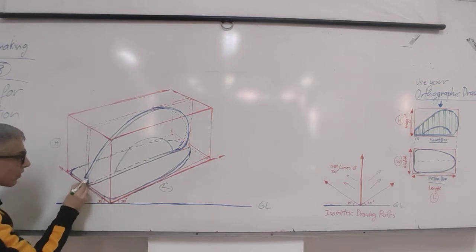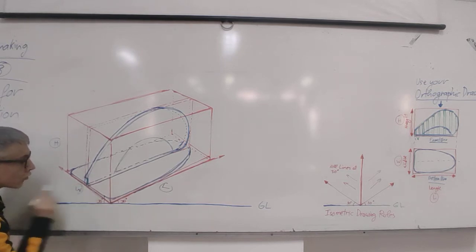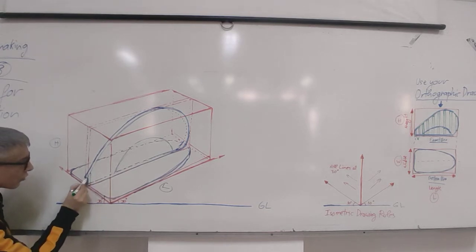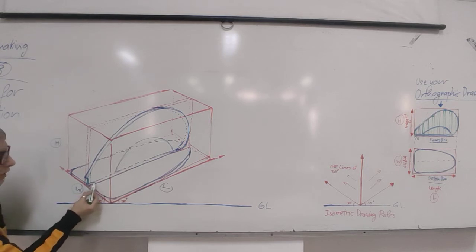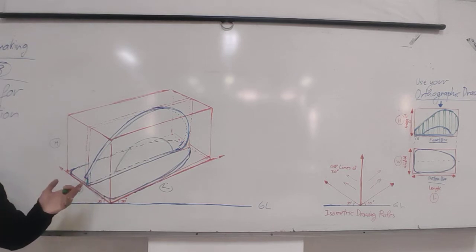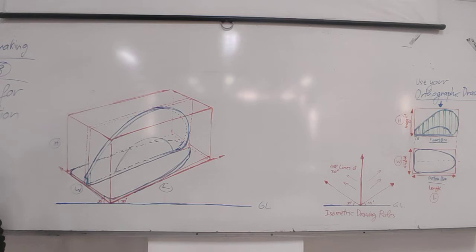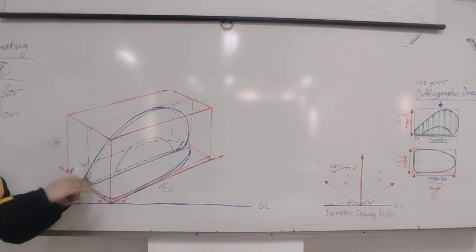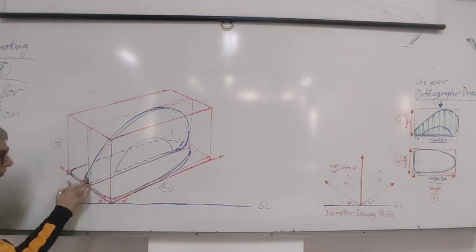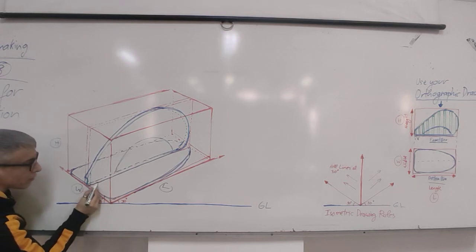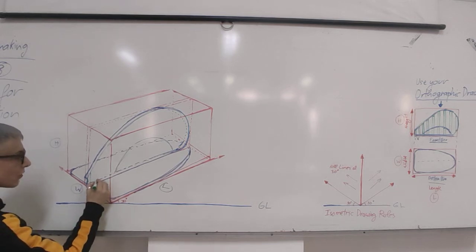So I will mark from here to here, 2 millimeter, I count, and I draw. Then I count 5 millimeter. You can do that on this line or on this line to start the same, okay? But start in the middle because it's easier later to transfer. Make sure it's exactly correct here. If you make a mistake, it will transfer to the final view later. So, 2 millimeter, then you leave 5 millimeter space, and then you draw another 2 millimeter.